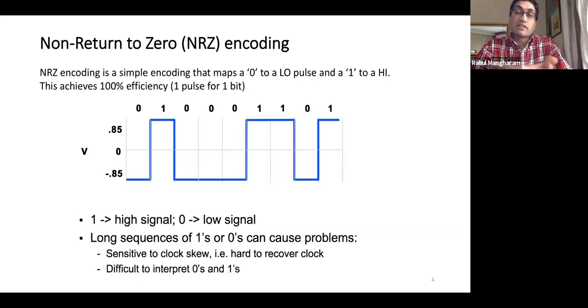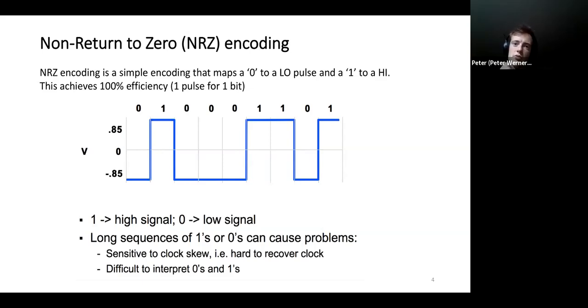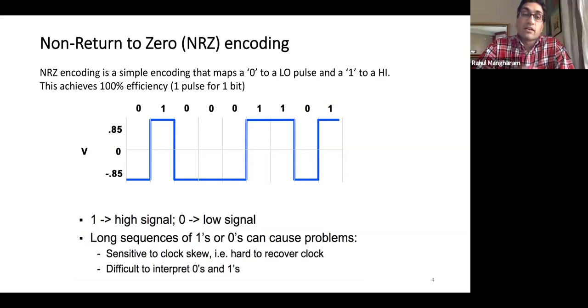So we have basically agreed offline. But what if you're off by half a clock cycle? Do you take a 0 or a 1? That's exactly the problem. Here we are essentially using the signal, when the signal has a transition, we're using that transition to say, aha, the signal I'm receiving has switched from 1 to 0, and therefore I know that this is the end of that bit.